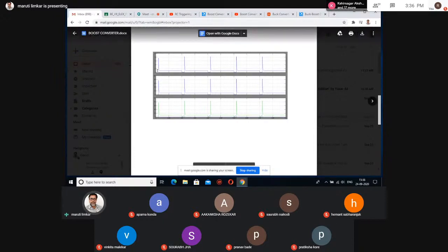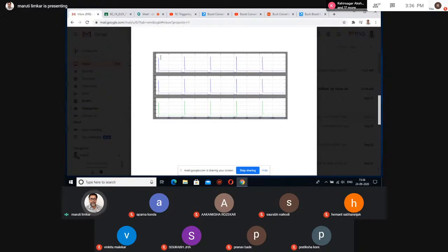Here the capacitor first starts charging up to Vc plus Vc, twice Vc, then it suddenly discharges. Each time we switch on, as soon as the switch is on, again the capacitor will be charged up to twice Vc. That is the supply voltage plus the voltage in the inductor, Vs plus Vs, twice Vs, then it will be discharged through the load resistor.